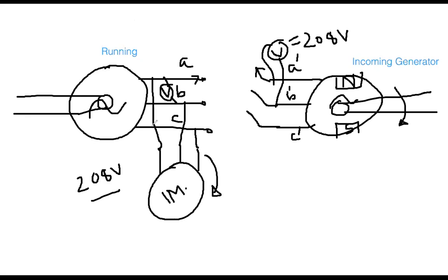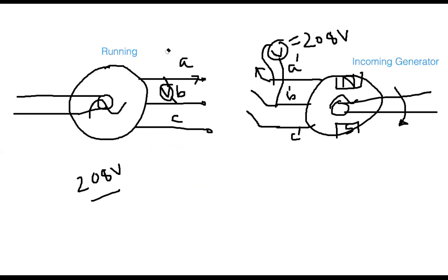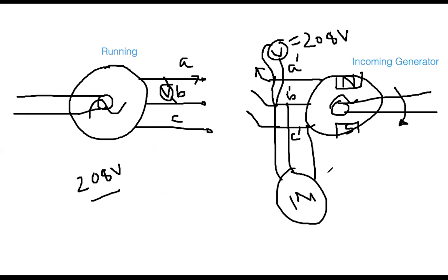So you notice that in the running system, or your existing system, the induction motor is properly following the given, prescribed direction. Now you take this induction motor out and connect it here. This is the same induction motor. It has three terminals. Again, you connect A phase, B phase, and C phase. And you notice that it is also rotating in the same direction, clockwise.